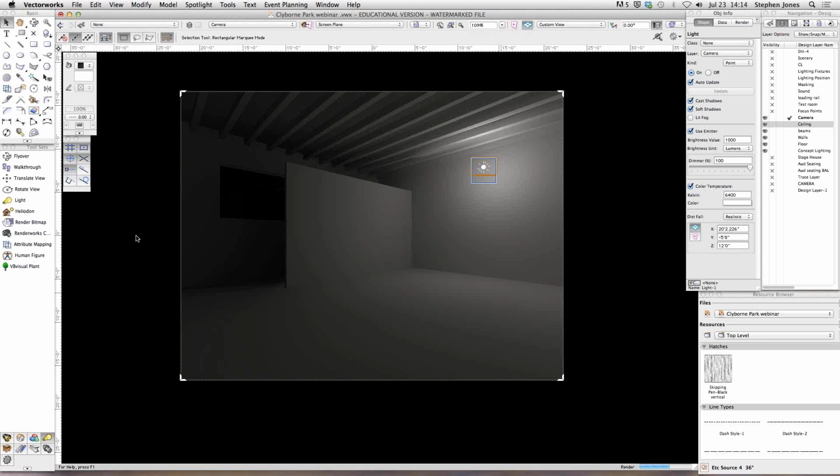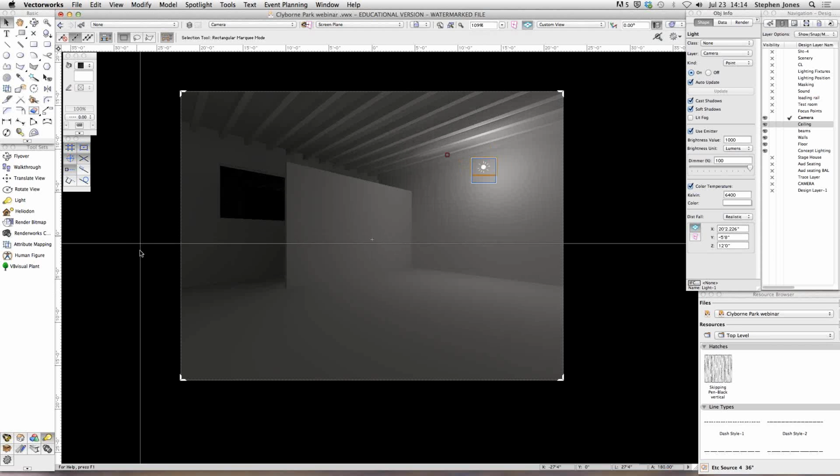And as my computer renders that out, we can see that now the light is bouncing off of every surface, and really I think this is one of the most realistic options that we have. So the normal 2 bounce I find is great for most renderings that I do. If there are not a lot of vertical surfaces to worry about, I find that it gives great depth to the image and to the scenes that I'm using, especially if I'm supplementing with other lighting fixtures.